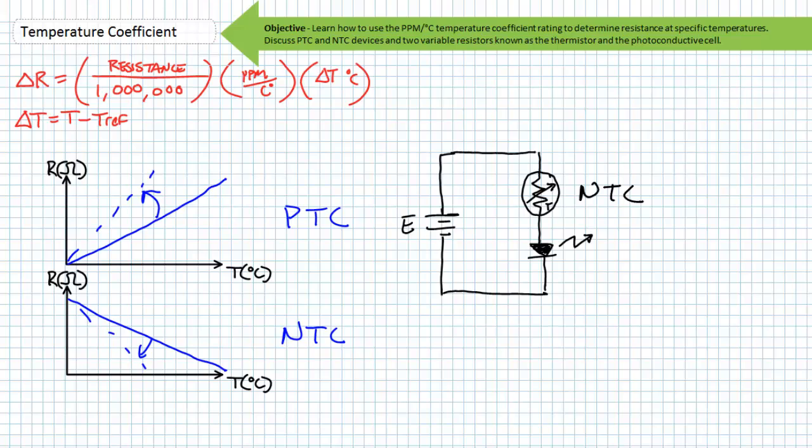Consider the exact same arrangement, however, using an NTC thermistor, i.e. one where resistance dramatically decreases with an increase in temperature. If the temperature is below a certain value, the resistance of the thermistor is high and allows for very little current to flow through the LED, so it remains unlit. As temperature rises, however, the NTC thermistor resistance value radically drops and the LED comes on.